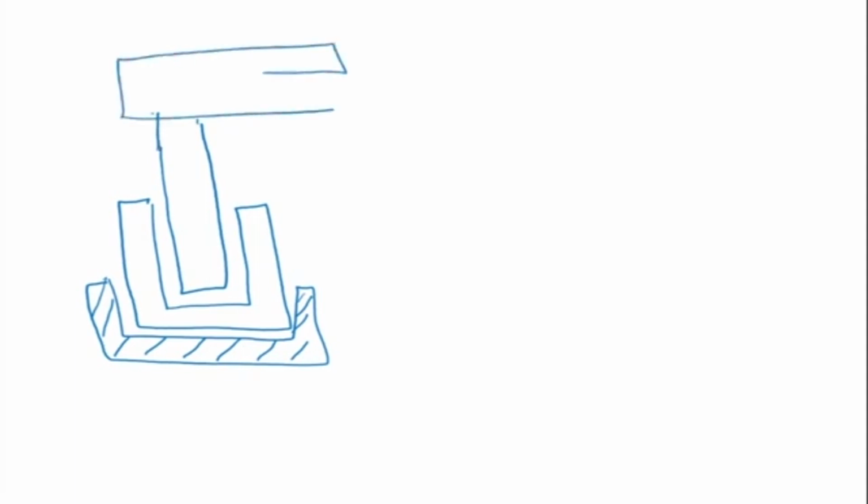Okay, so this is the base, and on this base we have a rotating joint. This can rotate, and inside this is a translating joint. So this is translating, and this translating one is here, and this is also a translating joint. The first thing we need to do is try to understand how this is moving, or what is moving where.